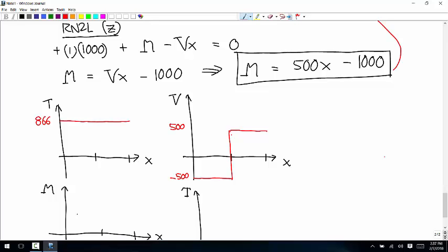Why? Well, that's how people do it. Really, what would happen for real is that the point force would be a distributed load spread over a very small amount of space. So it wouldn't be vertical, it would be slanted a little bit. But you'd have something going on that made this a continuous function. So we're just going to write it like this. But it's probably worth keeping in mind that, based on our simplification of this problem, we don't know mathematically what's happening at x equals 1.